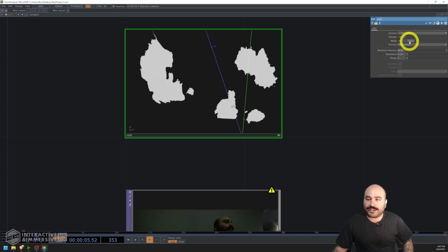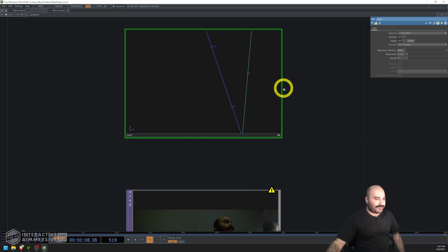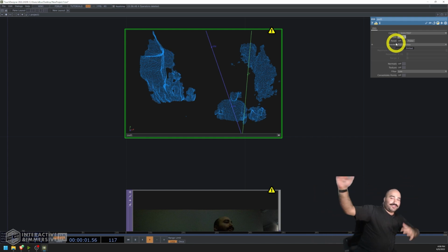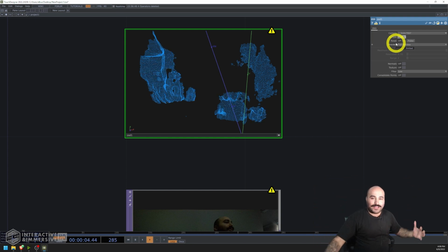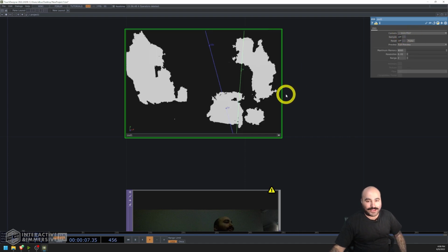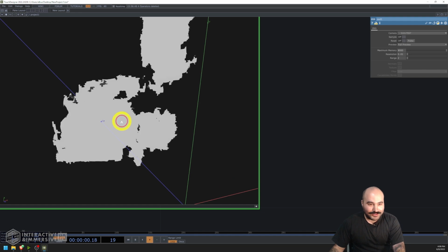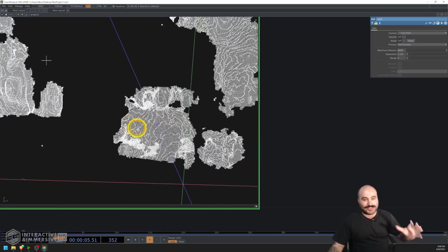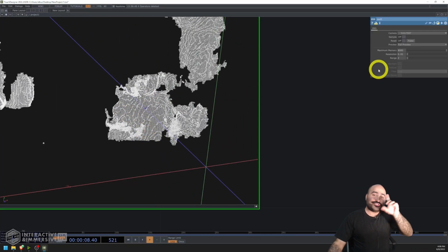So in this case, what I'm going to do is hit reset, get into position here for my scan, and set the sample button to on. And while you're doing this, I should say, the camera is the thing that should move, not the things inside of the environment. Actually, I can even do a quick example. If I start moving like crazy while that scan is happening, it's going to return to me the craziest mesh of a broken, 7-headed person, almost terrifying. But really, you should be still. And I'll show you the really cool part about how the camera can move in a second. That's why I'm trying to be really still when I hit the sample button, just for reference.